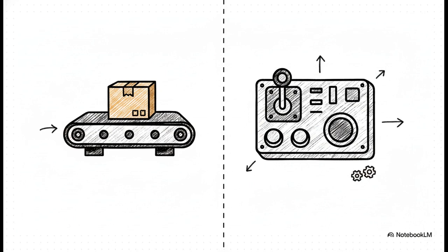The instruction path tells the system what to do. It sets the opcode. It essentially tells the switchyard, hey, I want to route my cargo through the boundary scan register, or maybe I want to route it through the device ID register. Once that instruction is firmly locked in, you transition over to the left side, the data path, to actually move the payload through whichever register you just selected. It is so perfectly balanced. If you understand the right side, you automatically understand the left.